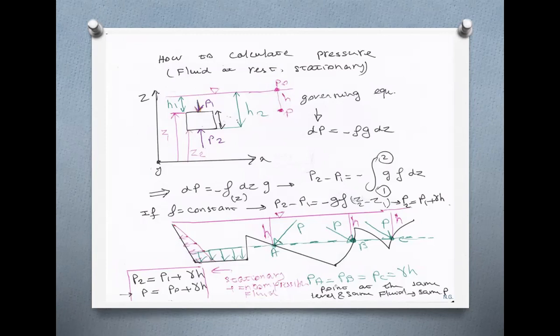Right. So in order to calculate pressure anywhere in the fluid, all you need is pressure on top of the fluid on free surface, which is usually, if it's exposed to the atmosphere, pressure of atmosphere. We name pressure of atmosphere P naught or PATM, ATM for atmosphere. P naught because we usually use it as a reference. I'm going to explain in a second. And set it equal to 0. So P naught is pressure of atmosphere, PATM or P naught, plus gamma H.